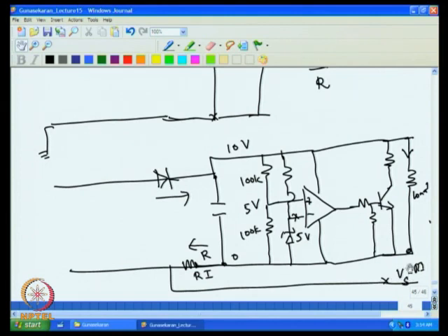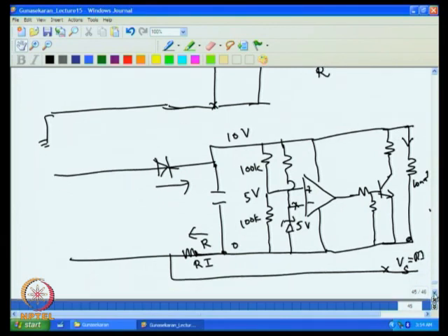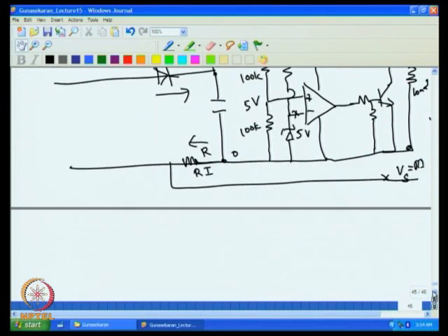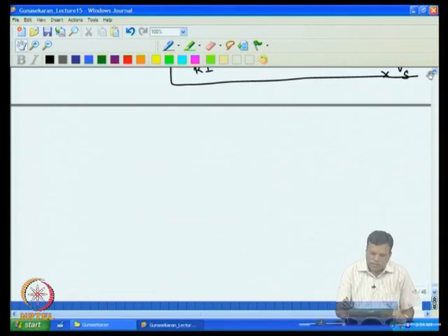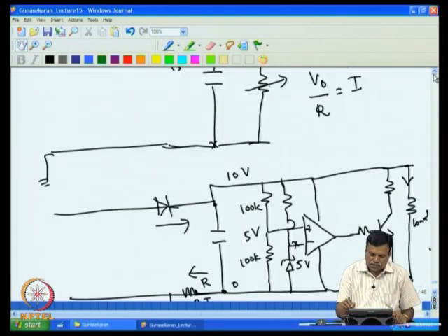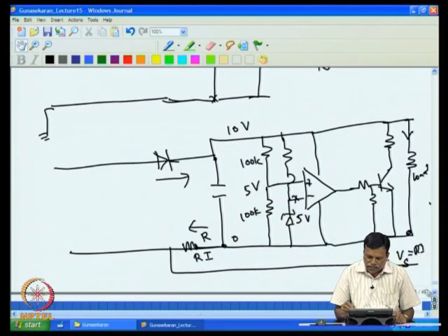You know, the voltage across this is proportional to the current that is flowing. So we have now used this regulated power supply voltage and this signal to activate some process. The first step would be to convert this signal voltage into a usable positive voltage, because if you see carefully, the voltage across this is negative, because this is our ground point and current is flowing like this.